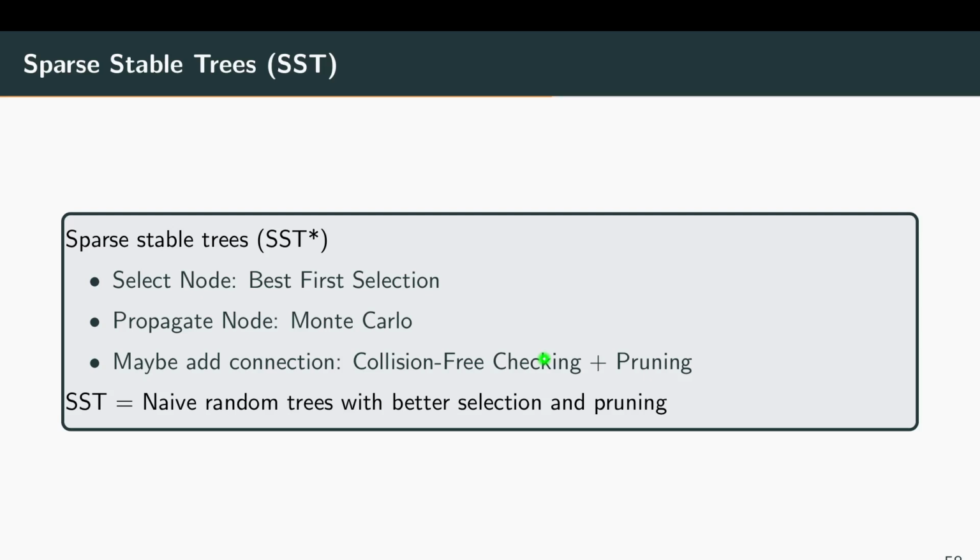Typically there are some weights in the distance metric. So you take maybe the Euclidean distance of the position plus the Euclidean distance of the velocity times 0.1. So basically the position part has a very high weight, and the velocity part has a pretty low weight. But the weighting is mostly done to normalize the different components. Yeah, I feel I confused you more.